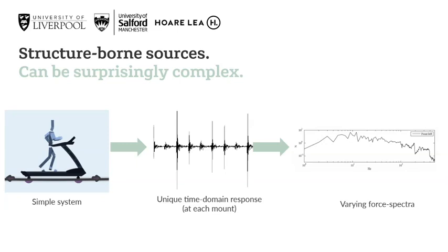We could reduce the treadmill and the user to a combined mass. We could think about the contact points as the spring between that and the structure beneath. And the disturbing frequency, the operating frequency, could be that of the pace frequency set by the runner.